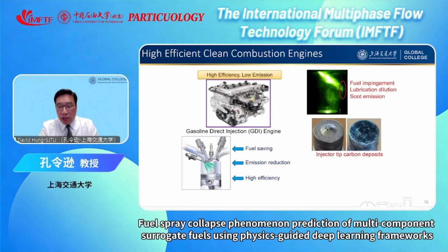This is a picture of the injector tip. You can see that there are 7 holes clearly when the injector is new. But after a while of engine operation in a very hostile environment, the heat, the mixing, and the residual fuel would clog up the injector tip. On the right, I don't think we can even identify where the holes are. If they are there, they could be partially blocked, completely blocked, or not fully functional.